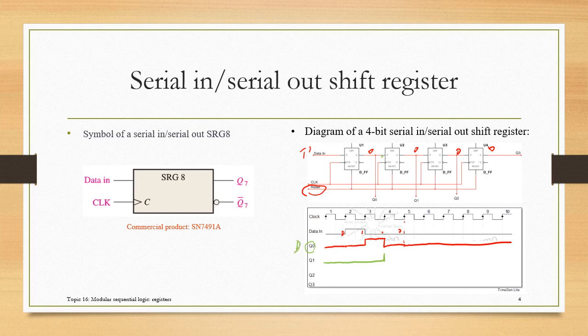But it will lag by 1 clock cycle, because you can think this is D1. Okay, so this is 1, 2, 3 here, or you can use D2, whatever. So I use D1 here. So D1, Q1 will follow D1, so it will be like this. Similarly, you will find Q2, because Q1 basically connects to D2, so Q2 will follow D2.